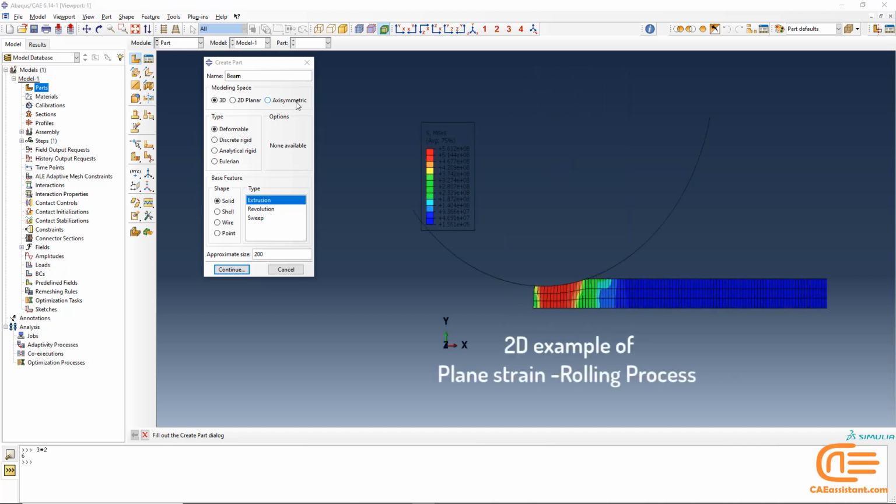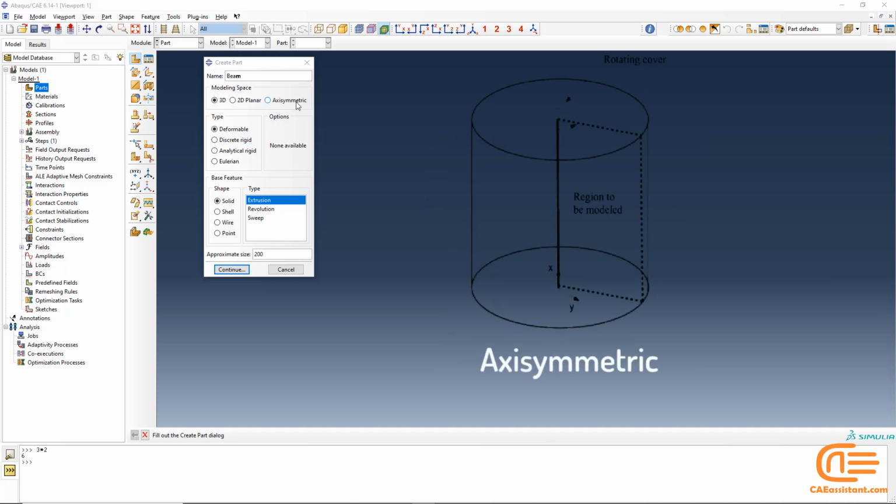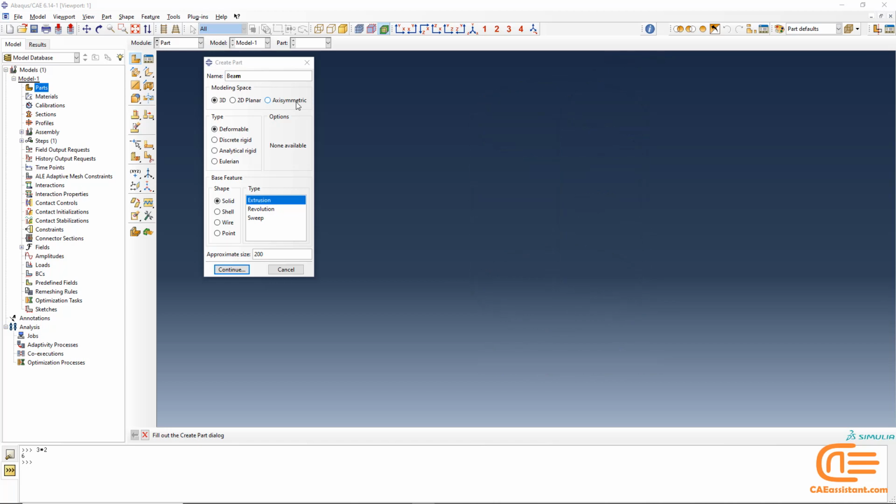Or if the thickness of the part is high, the cross-section area is uniform and the part length is long, by applying loads along the thickness, the problem is a plane strain. When geometry and loading have symmetry around the central axis, the problem is axisymmetric. The existence of both conditions is required simultaneously, and the lack of geometric or loading conditions makes the problem non-axisymmetric. Cylindrical, conical, and spherical vessels under internal or external pressures and many pressure vessels are axisymmetric problems.